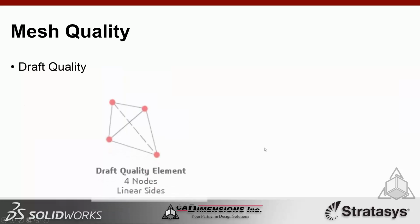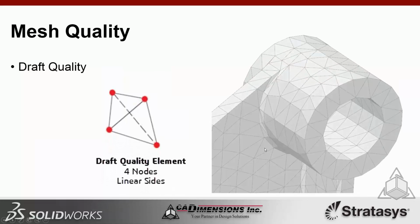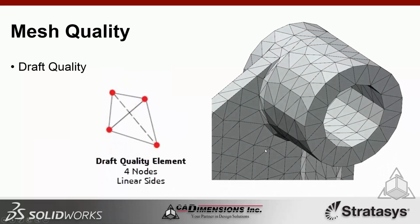Okay, so in the realm of solid elements, we have two options: draft quality and high quality. These are also known as first and second order elements. A draft quality element has four nodes and linear sides, or legs. The nodes are where the solver actually runs its equation, so it's important that these nodes and consequently the elements match up to actual geometry as close as possible.